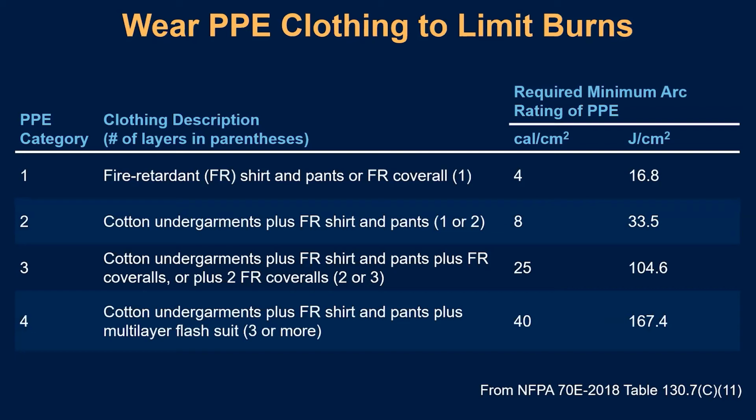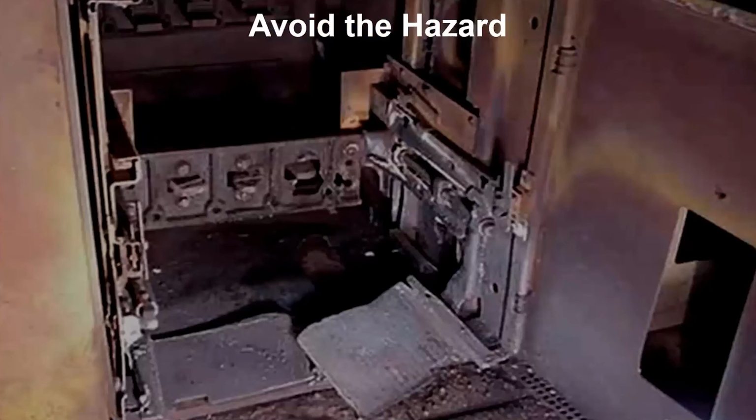So with all that said, in terms of the hazard, the best way to avoid the hazard is to eliminate that possibility, right? It sounds pretty obvious when someone says, try to de-energize the equipment if you can, but it's a good idea to think about it and reevaluate this option and see if you can eliminate that hazard by considering if that can be de-energized at some other time, and if that job can be done at a different time, and so on.